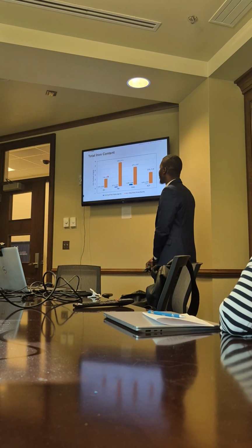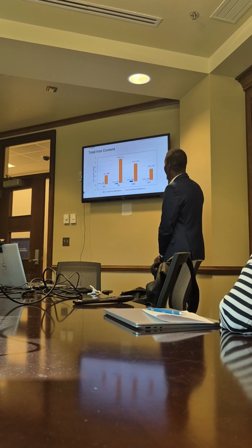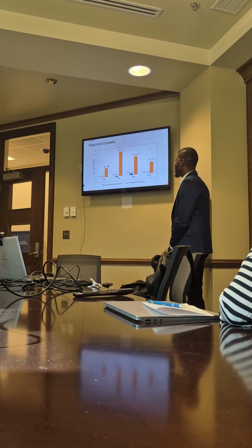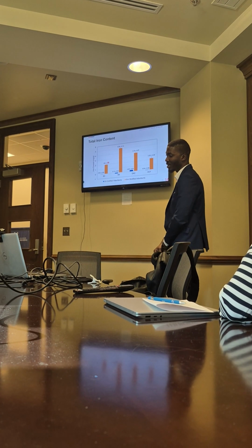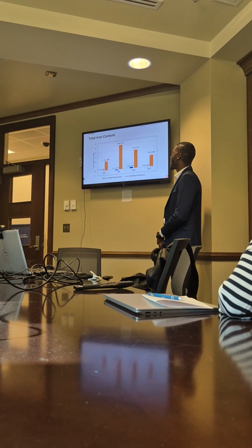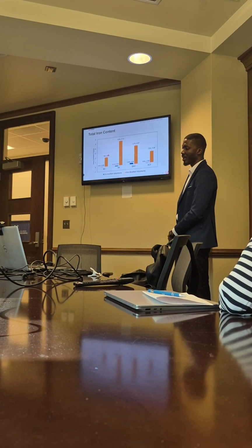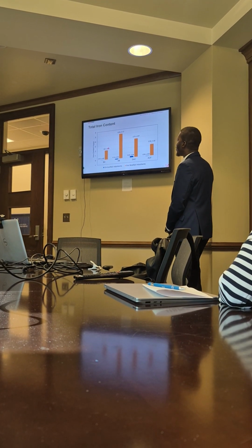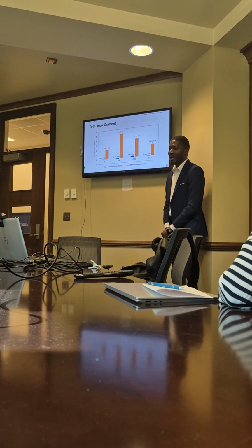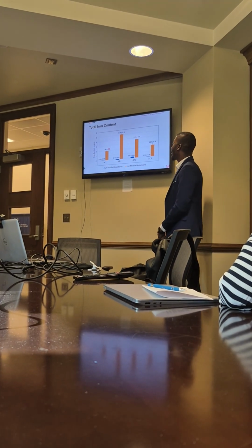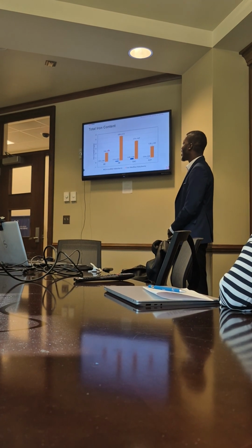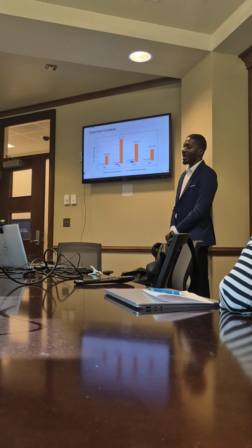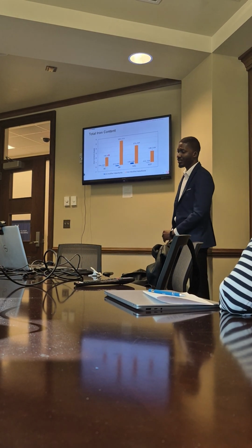So looking at the results, on our x-axis, we can see our adsorbents. The blue color signifies unmodified adsorbents, and the orange color signifies iron modified adsorbents. And on the y-axis, we have the iron concentration in milligram per gram. So before iron modification, we can see negligible amounts of iron present in our material. However, after iron modification, AB had the highest iron loading, followed by GAC, ACF, and biochar. So this confirms that we had iron loaded onto our adsorbents.